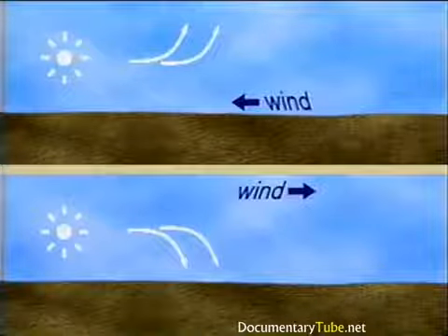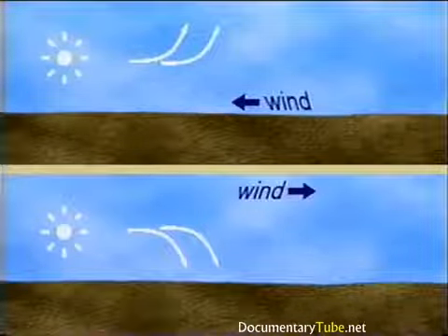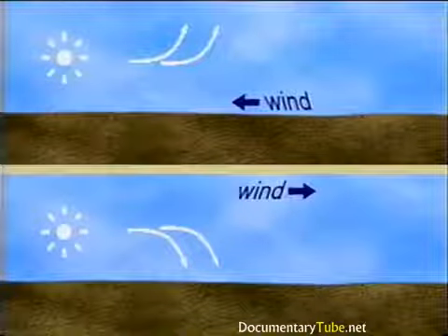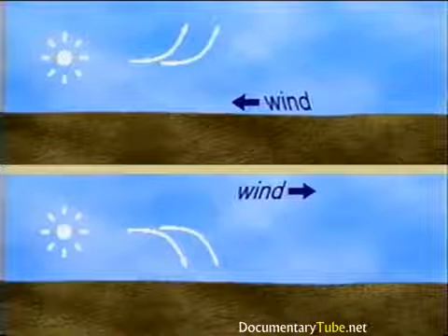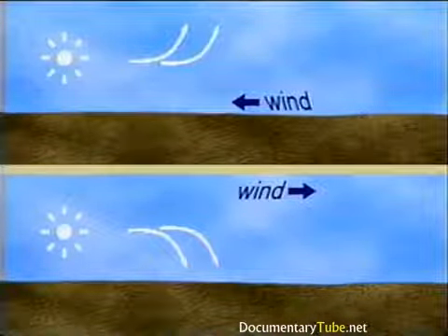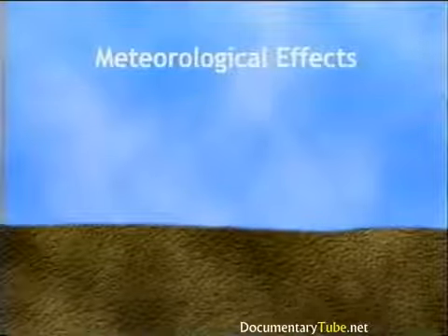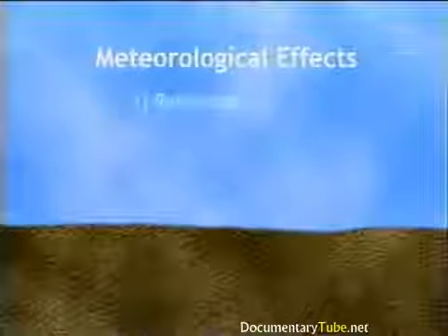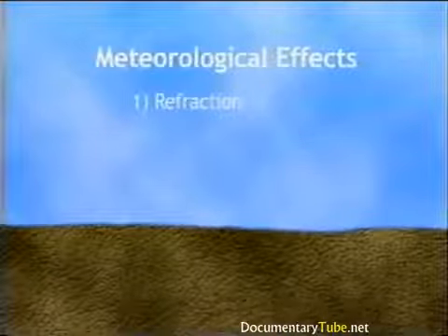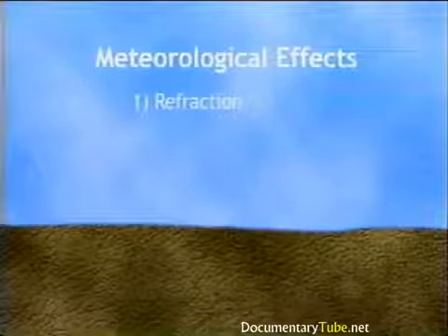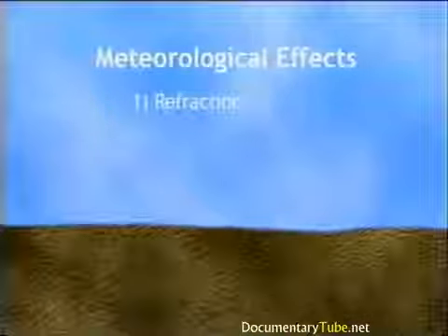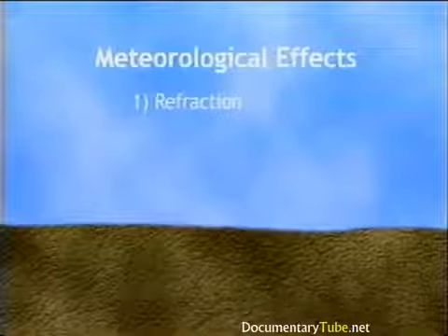And when sound is propagating downwind, the ray paths curve downward as with a temperature inversion, increasing the received noise level. The importance of meteorological effects is that sound may reach the receiver with greater intensity if it is refracted downward toward the earth, and with less intensity if the sound is refracted upward away from the earth, than in cases where meteorological effects are negligible.